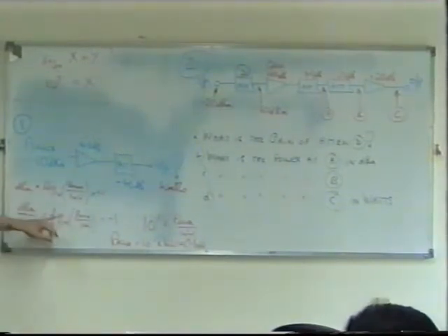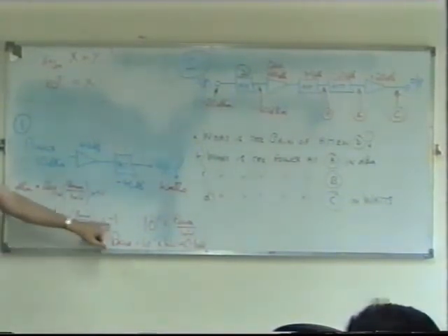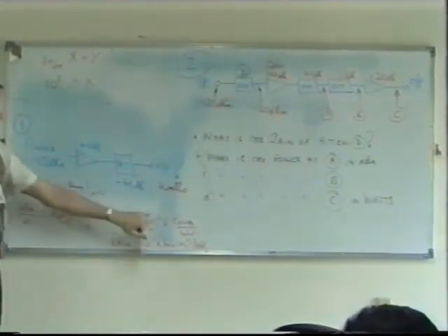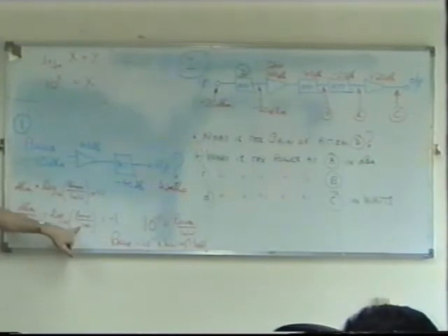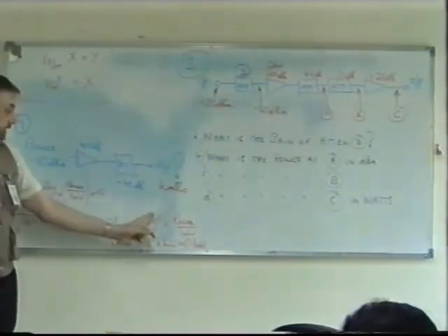So what it's saying is that the logarithm of this ratio is equal to minus 1. Or putting it another way, from our knowledge of logarithms, which you should already know, 10 to the power minus 1 must equal this ratio, mustn't it? It's just a rearrangement of this formula. So 10 to the power minus 1 is equal to the power over 1 milliwatt.